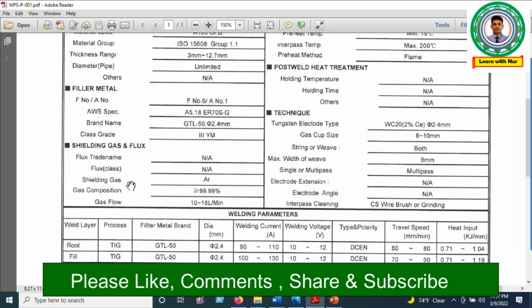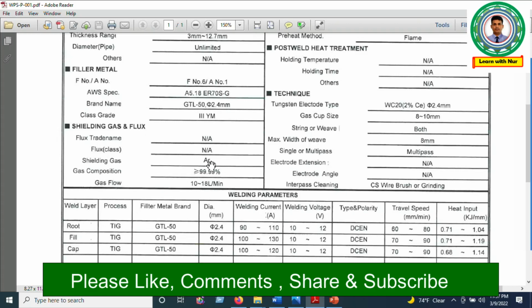We use shielding gas for the GTAW process, which is why argon is written here. So we will use argon for this WPS. Then gas composition is greater than or equal to 99.99%. This is the purity, so this gas should be 99.99% pure. Then gas flow rate, how many liters per minute: this is 10 to 18 liters per minute.